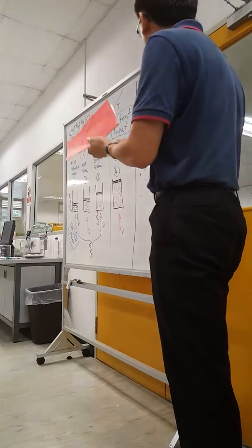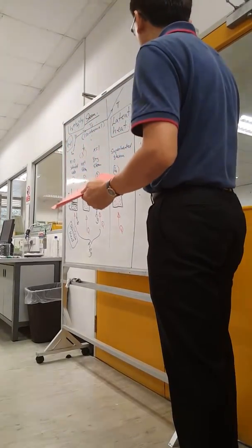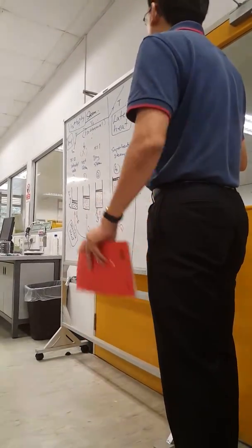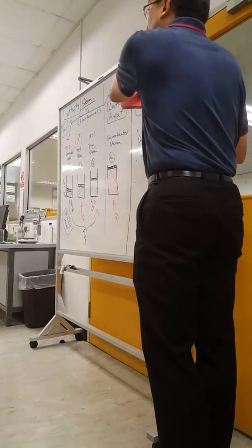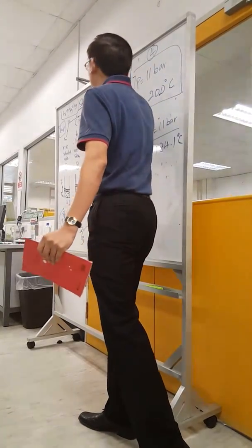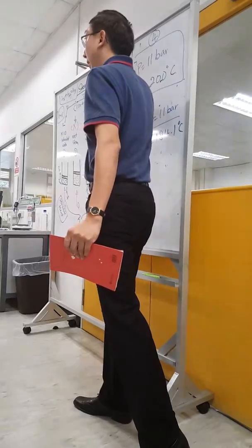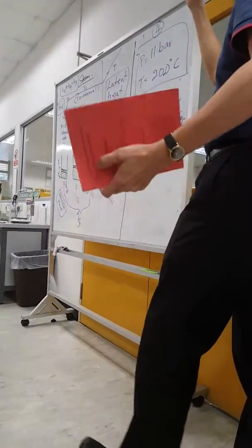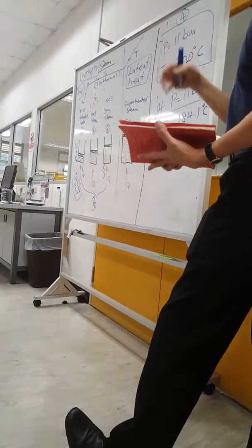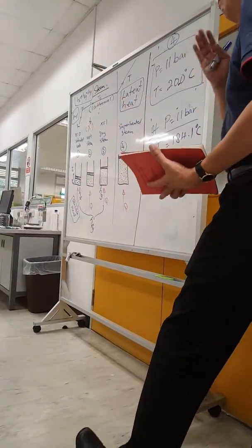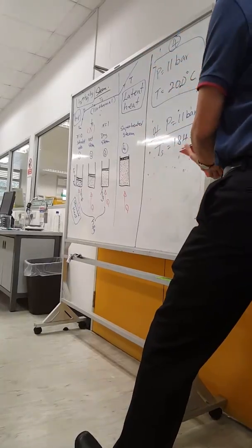So based on this, you'll know. You check a steam table at 11 bar, normally things boil at this. But now this thing can go above the boiling, that means the only way it can go is to stage 4. Any question? No? So when I give you pressure and all this sort of thing, when you read your steam table, you must know what stage they are in.